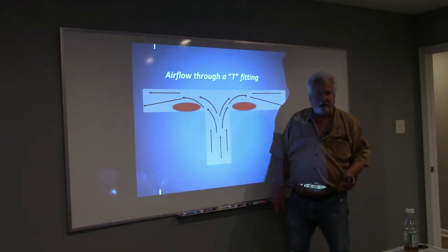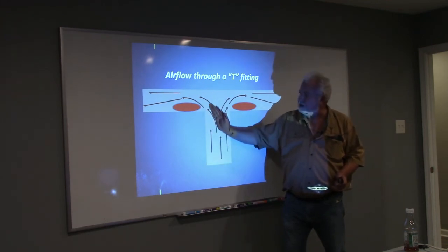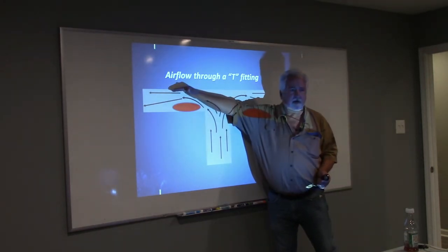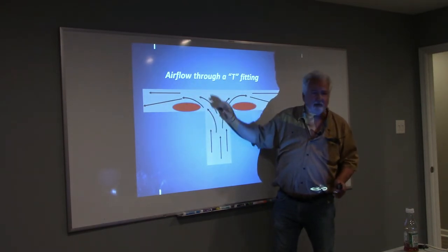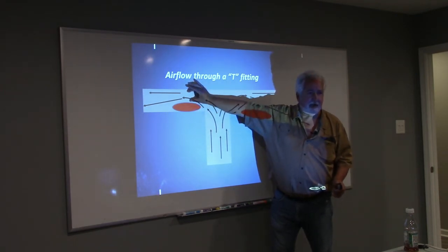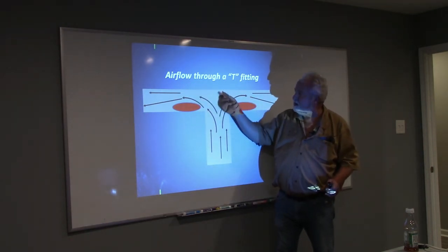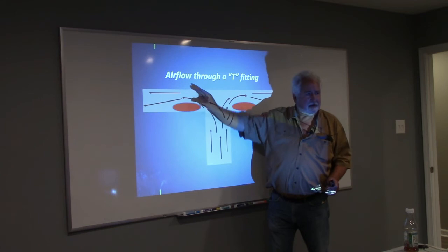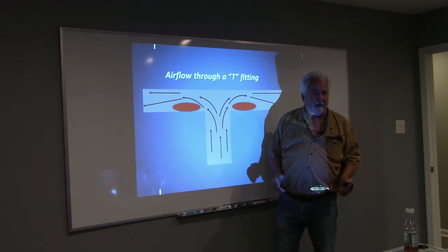So look at this 90 degree. Hunter, what happens on a 90 degree as it tries to make that corner? Where does all that air go? Slows down, right? It's going all the way to the top up here. What happened to the amount of space I'm using when I have to go around that 90 degree? I just reduced the amount of space to half. Wow, that's not good. So I've got a very high pressure build up here, and that 90 degree is making that just take up a little bit of space in that ductwork. I'm sure that resistance is starting to get very high right there.